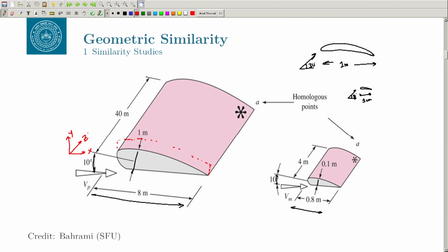So, at some height across the boundary layer, let us say 0.05 mm, you are measuring some force, let us say you are measuring the velocity. At some point your velocity is in this direction. If you are doing the same on the prototype, because it is scaled by 0.1, you have to go to a height which will be 0.005 meter, because it was 0.05 here.